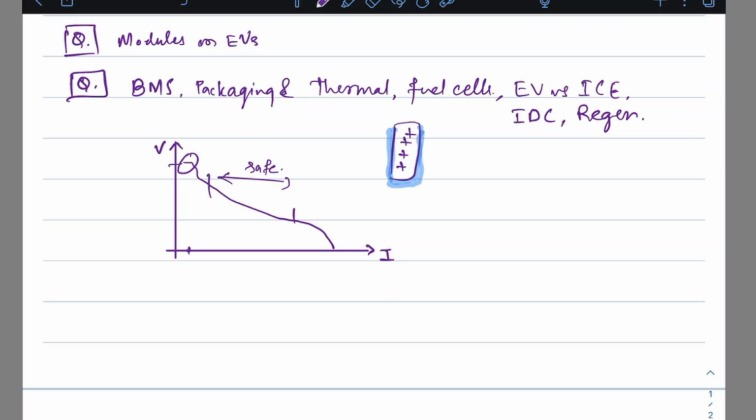Okay, sir. Vijay also asks another subtopic would be on driveline. I believe there is no gearbox in electric vehicles. So electric vehicles may or may not have a gearbox. Sometimes you need one to step down your RPM and improve your torque, because of the motor type and motor size you are constrained to work with. Sometimes you do not need a gearbox.